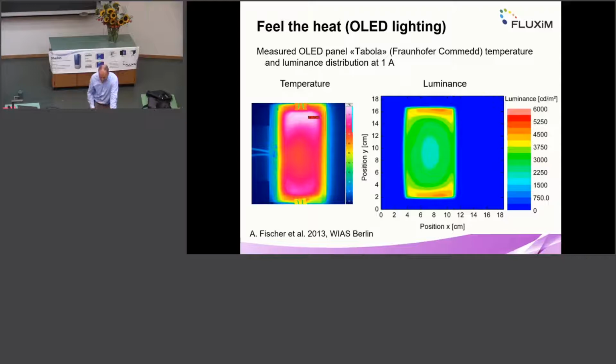So that's just an example of a non-uniform OLED panel. I don't know much more about this. Maybe you can say something about it. The potential comes from the outside and the conductivity is close to what you apply, but then as you already explained, it will drop towards the middle. There was no metal grid. No metal grid. A drastic example of how sheet resistance and thermal effects can then decrease the luminance in the middle. So a bad example on purpose, kind of, yeah.